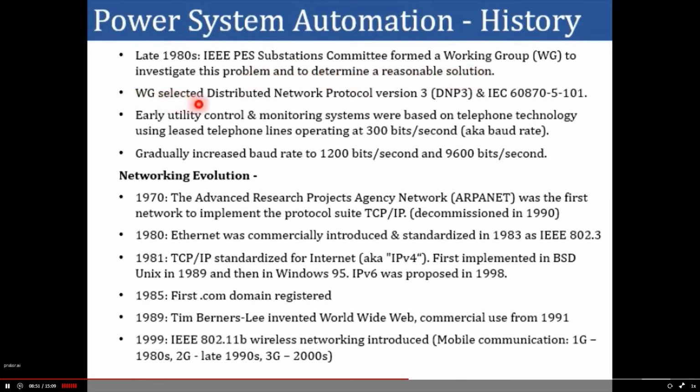So that working group finally selected Distributed Network Protocol version 3, called DNP3, and IEC 60870-5-101 as the open standard protocols for SCADA communication, so that the vendors who integrate and the suppliers who supply the devices and the software can make sure that their solutions and devices are compatible with the DNP3 and 60870-5-101 protocols.